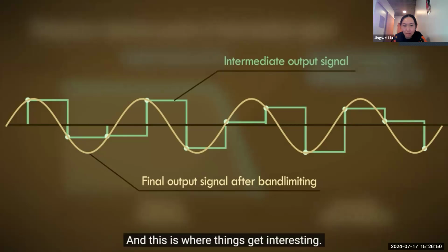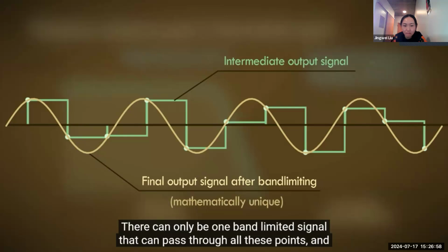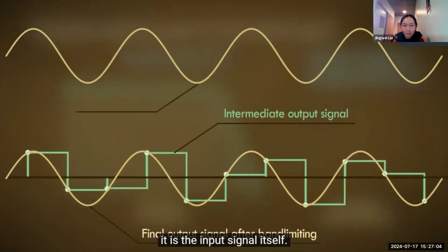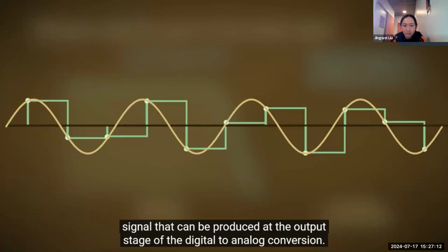And this is where things get interesting. The signal produced that goes through all these points is a mathematically unique solution. There can only be one band-limited signal that can pass through all these points, and it is the input signal itself. So the input signal passed through the analog to digital conversion step is the only possible signal that can be produced at the output stage of the digital to analog conversion.